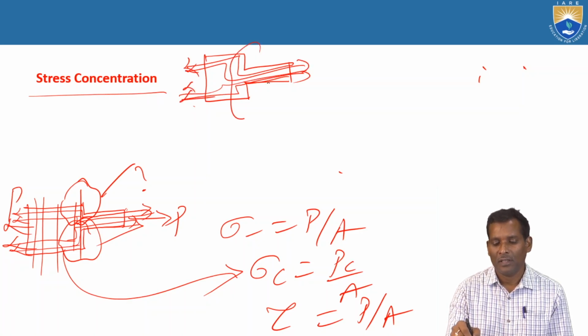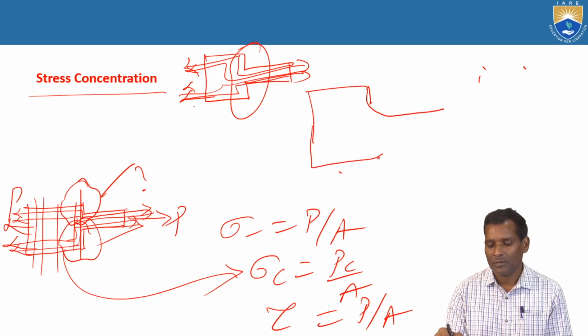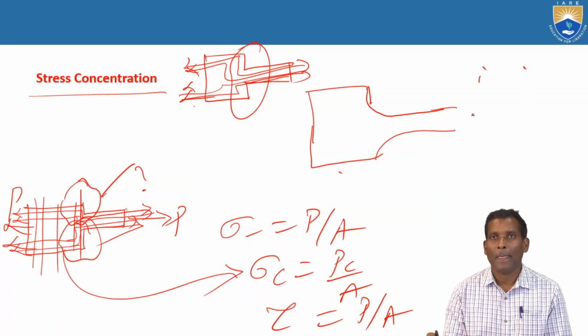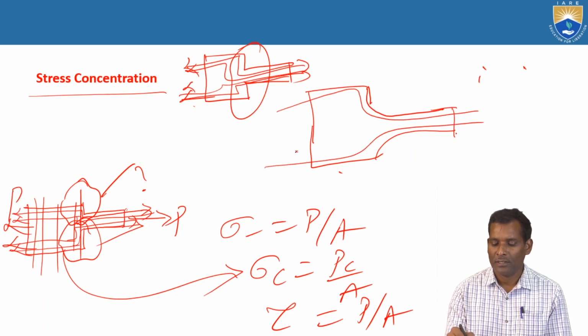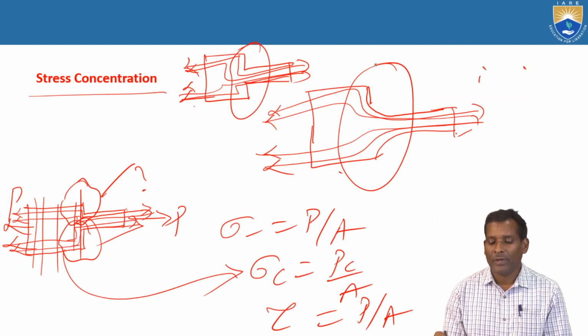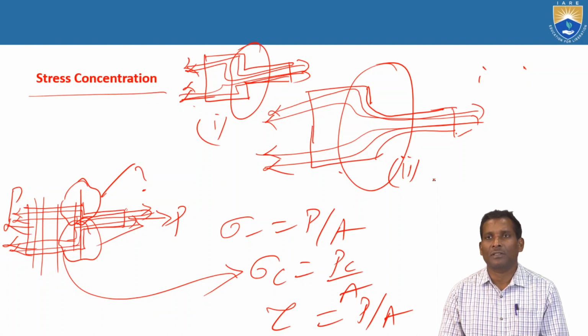Here more stress concentration will be present. To avoid it, create fillets. Due to these fillets, smooth flow lines will be possible, so in this region, compared to the previous one, the stress concentration will be somewhat reduced.